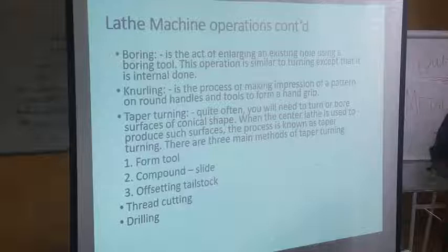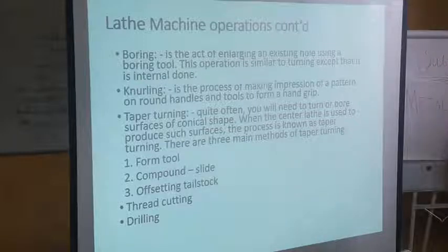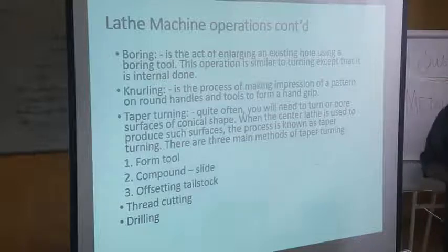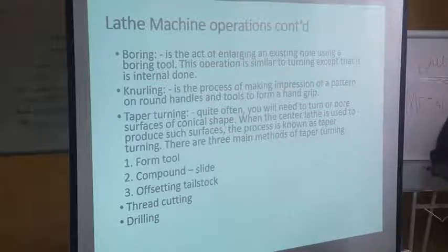The next is boring. Boring as an operation on the lathe machine is simply to enlarge the diameter of an existing hole. Before you carry out boring operation, we know there are other machines used to carry out several operations.